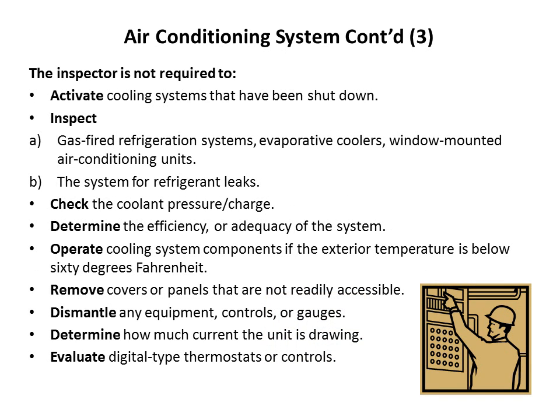The inspector is not required to activate cooling systems that have been shut down, inspect gas-fired refrigeration systems, evaporative coolers, window-mounted air conditioning units, and the system for refrigerant leaks. Check the coolant pressure and charge, determine the efficiency or adequacy of the system, or operate cooling system components if the exterior temperature is below 60 degrees Fahrenheit. Doing so will damage cooling equipment.